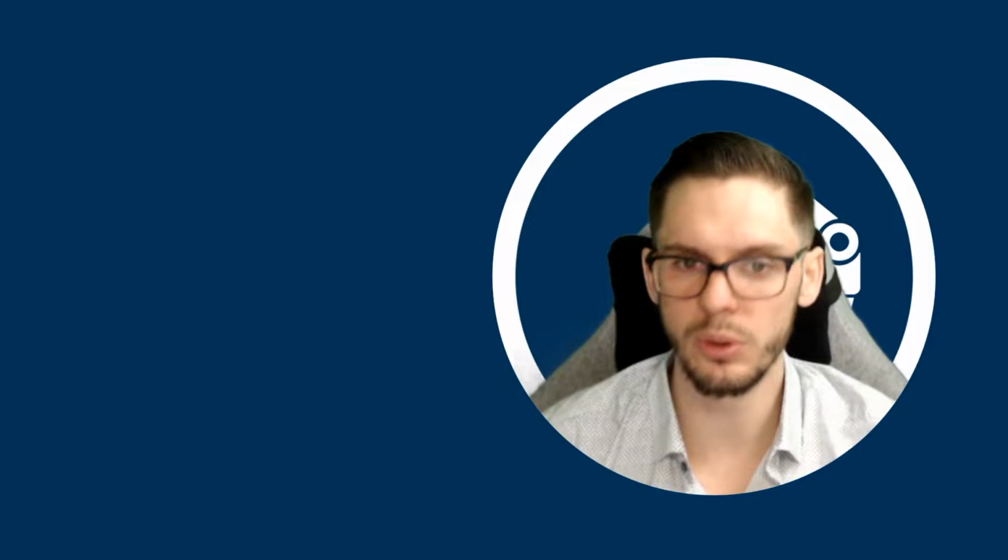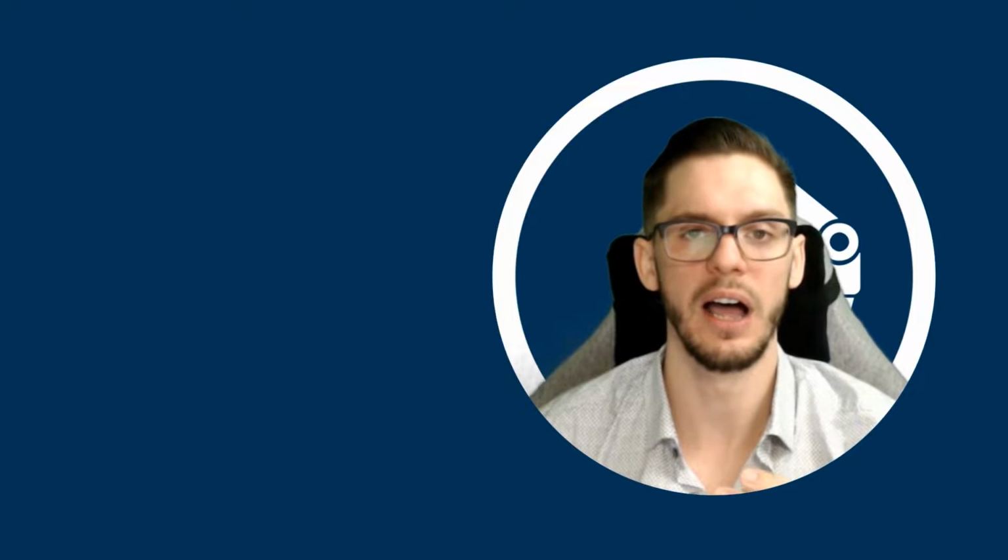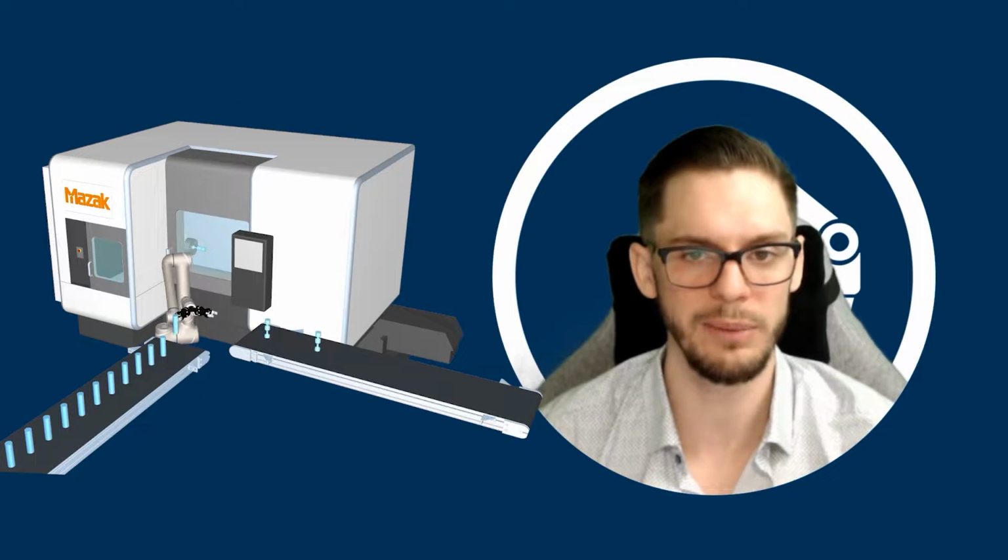And for the next example, we will be a bit more creative in our usage of the mechanisms. Why not simulate a conveyor or a CNC door? You will soon realize that custom mechanisms have way more potential than it appears at first in terms of creating a more realistic robotic station. It can even be very useful for offline programming. It can help you take into account any moving parts, like a clamp, for example, in the collision detection process.